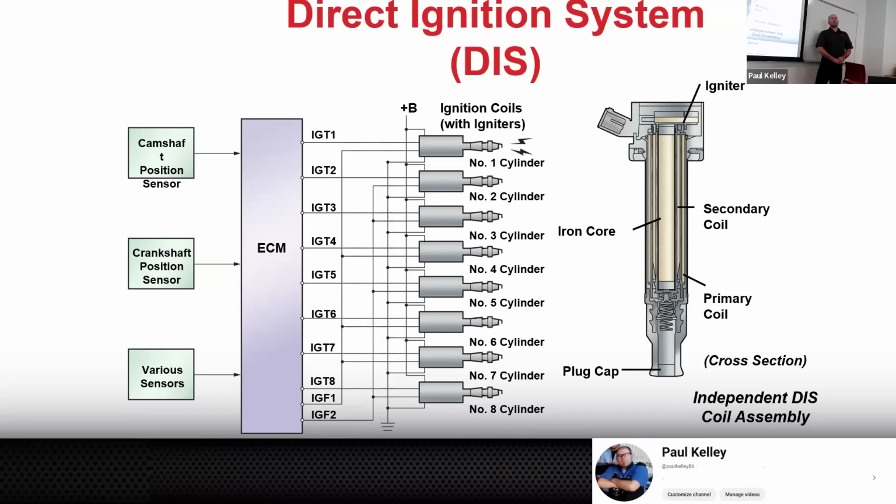If your spark plugs were due at 100 and the car's got 200 and it's misfiring, it may very well be the spark plugs. But because we came from the era of tune-ups, a lot of times, every time somebody gets a misfire, they're like, oh yeah, I need spark plugs, put spark plugs in it. So spark plugs tend to still be over-maintained, because people think spark plugs don't last 10 years and 100,000 miles, they last 1 or 2 years. But no, not the $15 NGK iridium coated. Those are 10 years and 100,000 miles. So just weigh all that out to give you some good perspective.